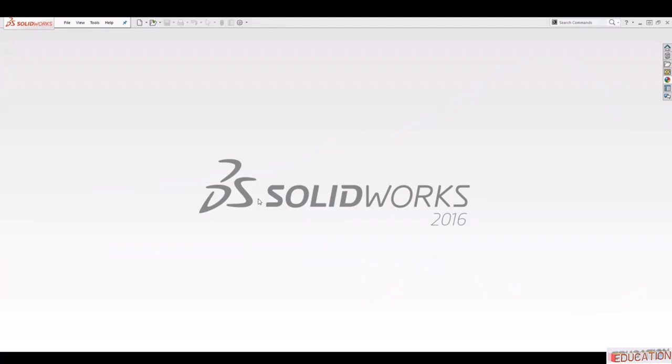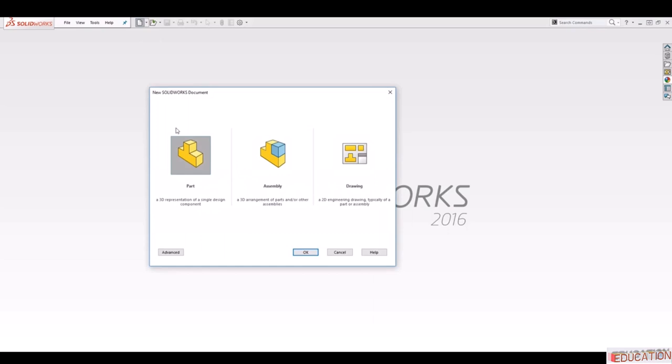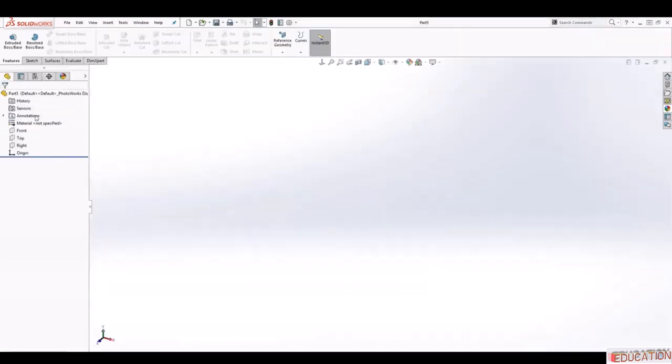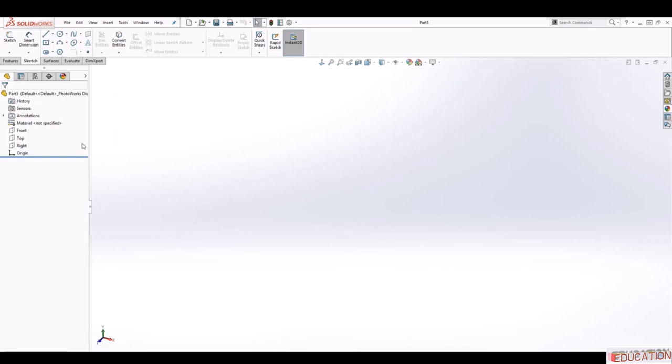Hello, welcome to another lecture. In this lecture, we are going to be talking about sketch planes, what they are, and how to make one. So to start, click on new part. Okay. Now, in order for you to draw any sketch, you always need a plane to draw your sketch on. And these are your sketch planes over here. We have the front plane, the top plane, and the right plane. Those are the three main planes SolidWorks gave you.